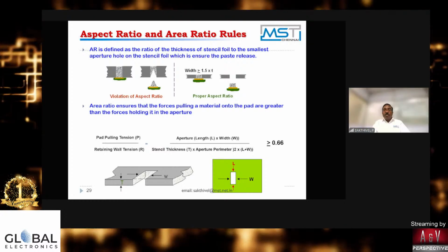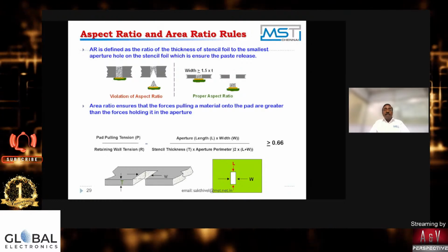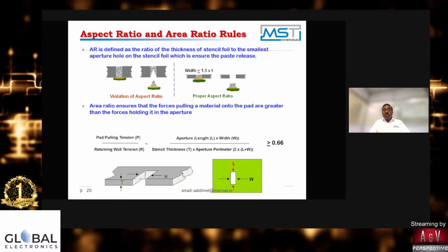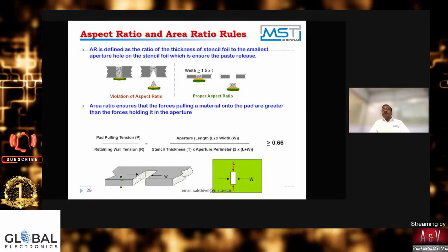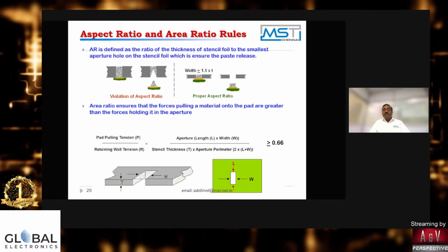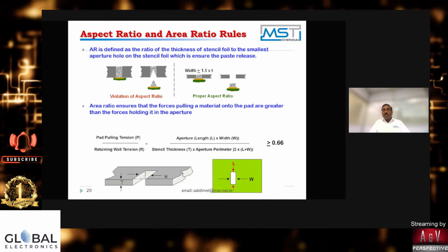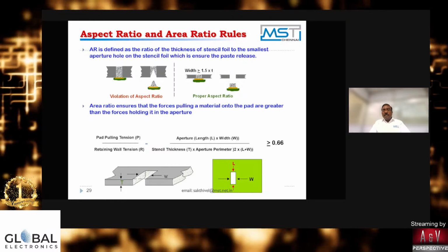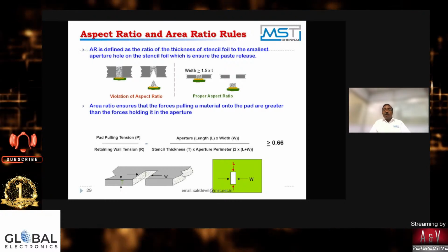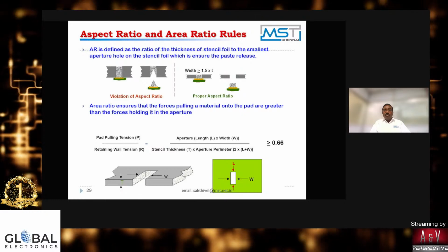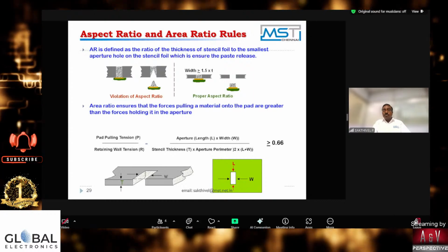And for people using it in mass production, high volume production, more than 10,000 per day, we strongly suggest they go with this surface finish, wherein it extends the lifetime of the printing and the production time is reduced. It improves timing, productivity, and indirect cost saving on consumables. There are many indirect advantages, but the straight advantage is better paste release. You don't find any insufficient or high volumes in the printing area, so your line is running 100% free.